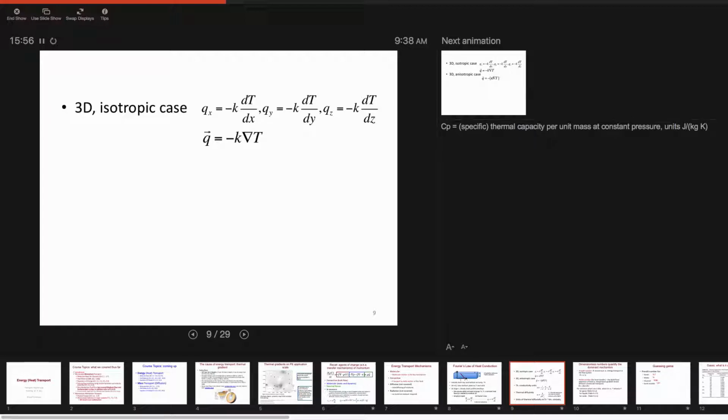In terms of geologic materials, typical heterogeneous materials that are built from plates like that could be some of the shales or some of the clays if they have plate-like structures within. Because clays can have platelets, and those platelets are aligned in a certain direction. So cross direction versus along direction will have different properties, both in terms of conducting fluids, permeability, and in terms of thermal conductivity. Okay, so in the anisotropic case, the most general case, this conductivity is a tensor. And this tensor is applied to the vector, which still gives me vector Q as a result.